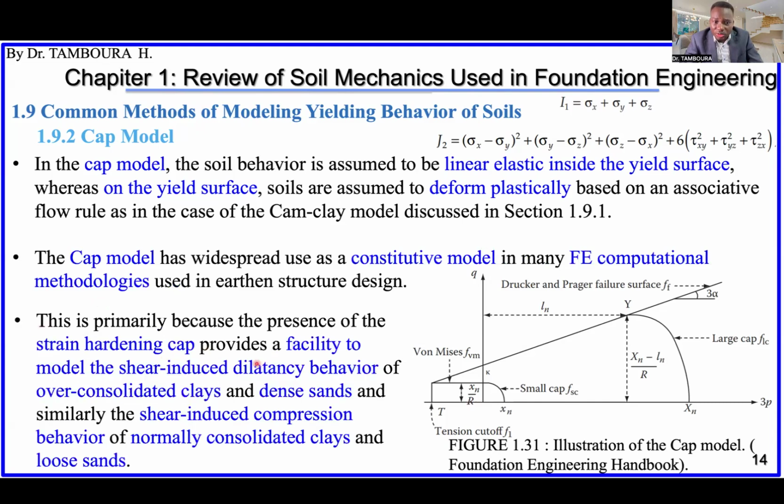And this is because the model is able to represent many types of soil in many situations. For example, in the case of modeling shear dilatancy behavior, which is in over-consolidated clay or dense sand, the strain hardening cap will provide help.